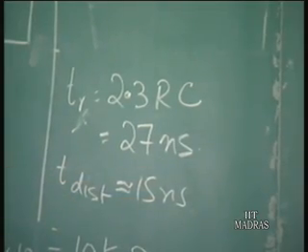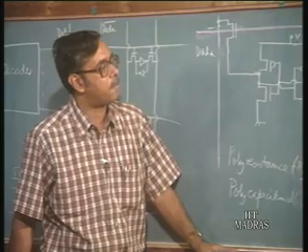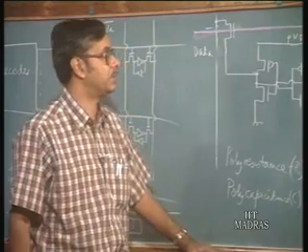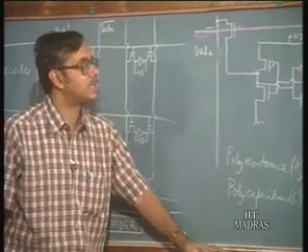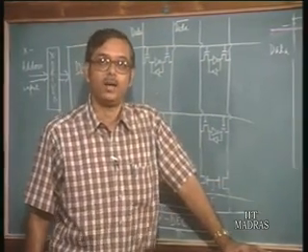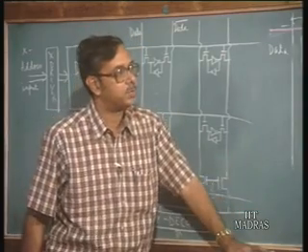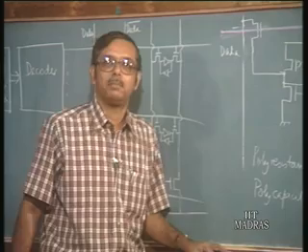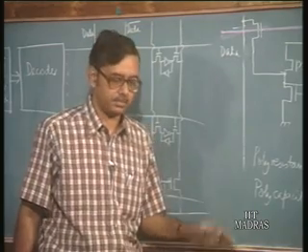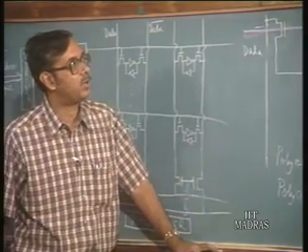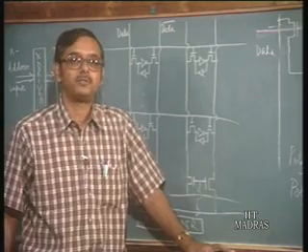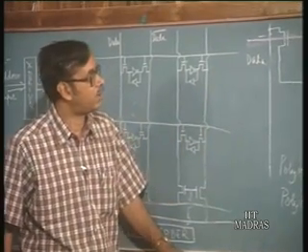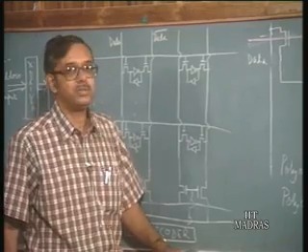So, this is the order of delay of this word line. This is an appreciable part of the delay of a memory cell, the time required to access a particular memory cell. Obviously, we have already studied bi-CMOS drivers, and we know that bi-CMOS is capable of driving large capacitances. So, instead of CMOS drivers, we shall be using bi-CMOS drivers.